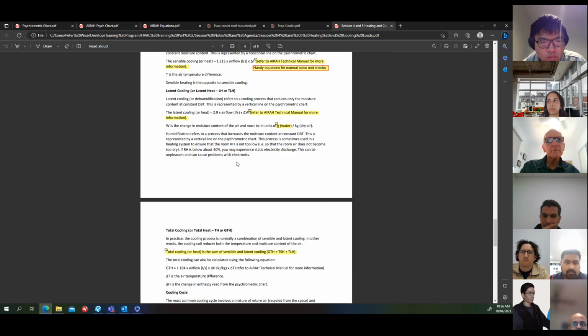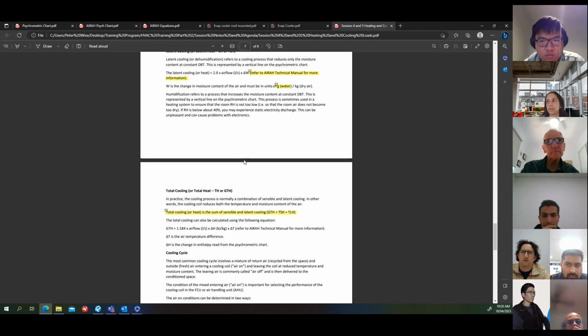And also, particularly in a data center, which is critical, but even a comms room, if the humidity gets too low, that can cause problems with electronics. And I have experienced this, that generally you're cooling, but if the humidity goes below 40%, sometimes you can get arcing with electronic components, and that's bad because they fail.